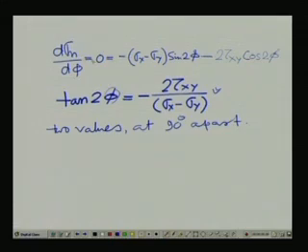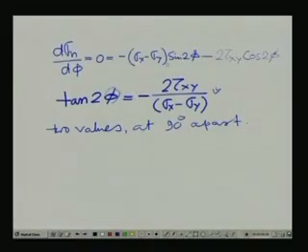That means whenever the normal stress is maximum or minimum, the shear stress comes out to be 0, because this expression is exactly the same as the shear stress expression we derived just earlier.